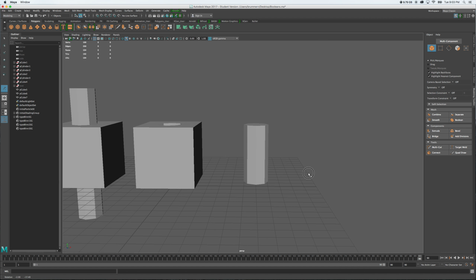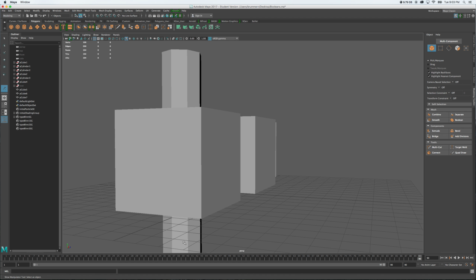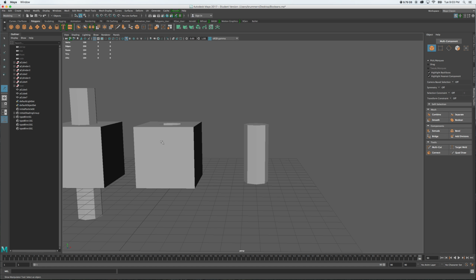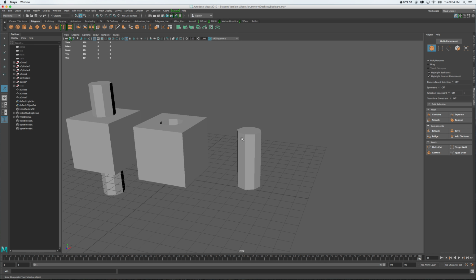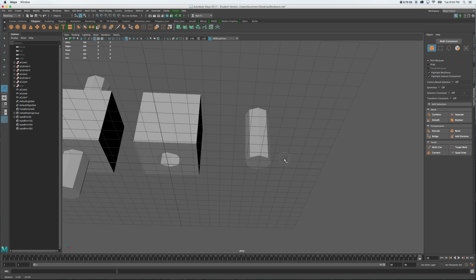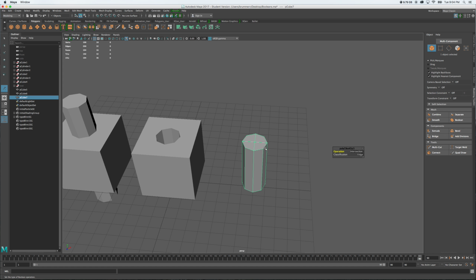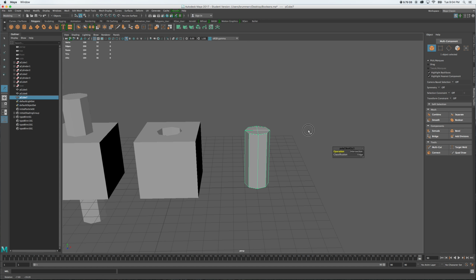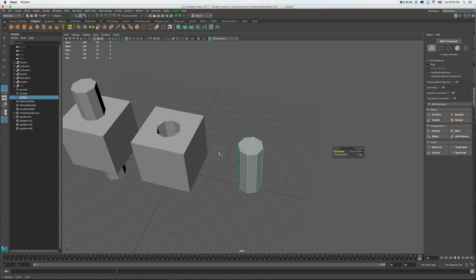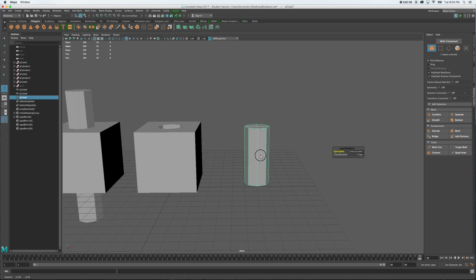But you'll notice what it did is it removed everything above and below from here, and it removed the additional cube. So it only gave me this cut. Had this been a sphere, I'd have a rounded top here and here on my cylinder. For this operation, I don't have to do anything to clean it up, mainly because the two original objects bore out a very clean final object.